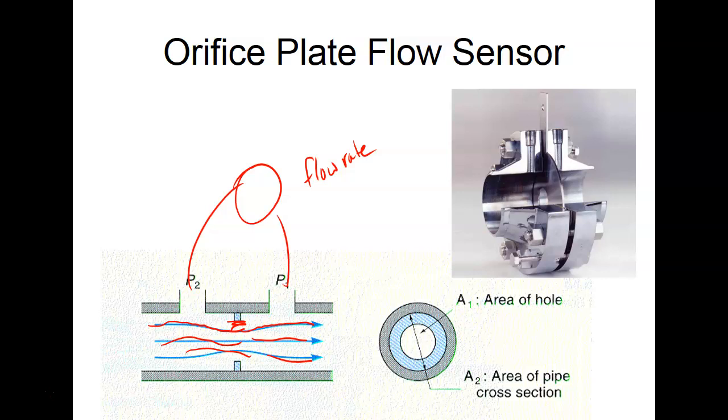So one of the guys in the thing that was talking about said that a flow control valve doesn't change pressure; it changes rate, and that's not true. Because you can't meter the flow without changing pressure a little bit, right? In fact, one of the labs that we do in fluid power is we put a pressure valve across the flow control valve. And when we put it down, you'll see it give a little pulse. Now, when the flow stops, the pressure is the same, right?